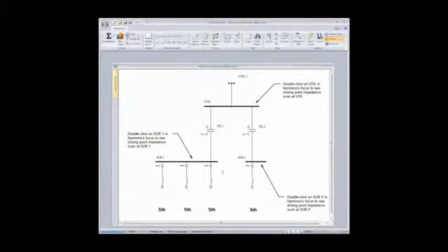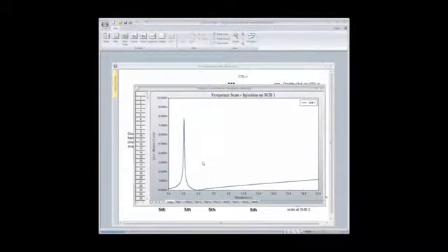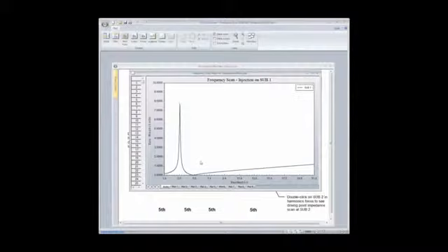However, if we were to put, for instance, a fifth harmonic filter on here that's been tuned at the fifth harmonic, and we double-click at this bus, we get exactly what we would expect. We have a filter that has a first parallel resonant point. That's one of the issues with notch harmonic filters that we have to be careful of, and I have a couple notes on that I want to go over.